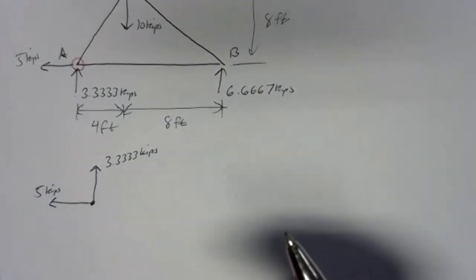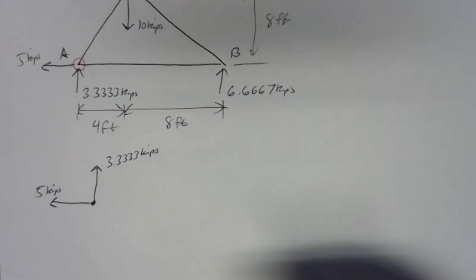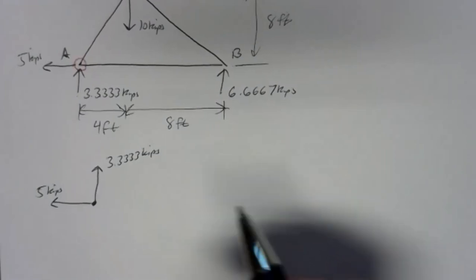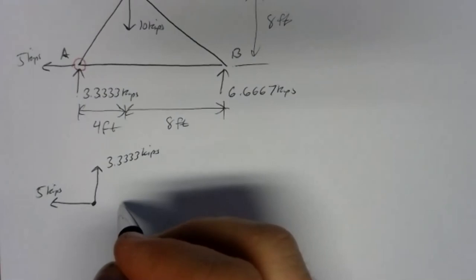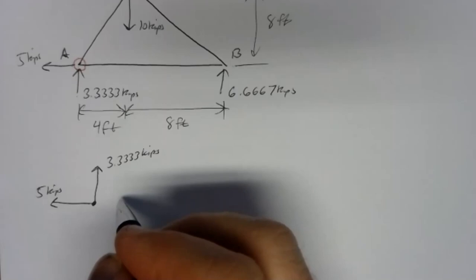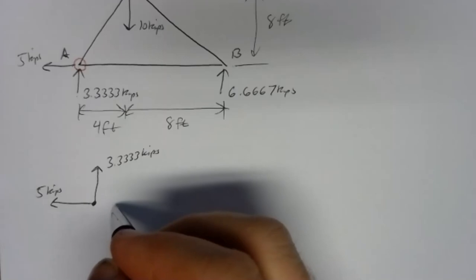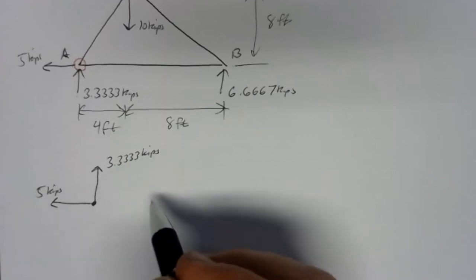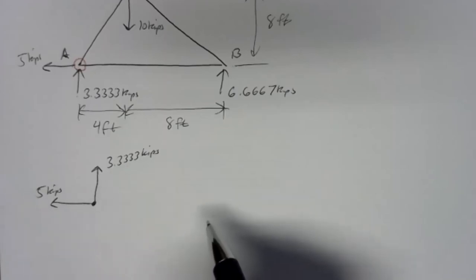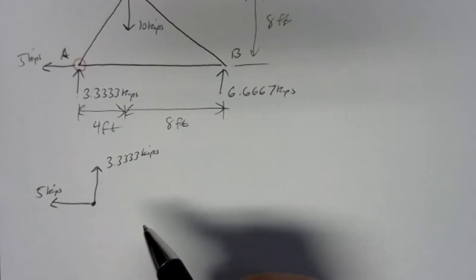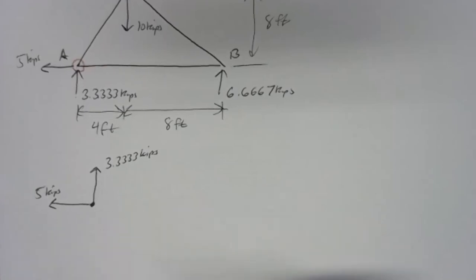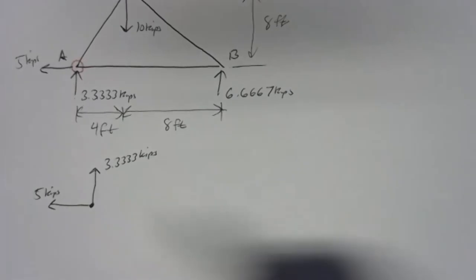And it's not always going to be clear what direction that force is in. Sometimes you just pick which direction based on what's going to be easiest to draw in the free body diagram. So you're going to make guesses here, and hopefully they'll be intelligent, educated guesses, and a lot of times they will be, but sometimes it's complex enough that you really can't make a good guess. So be assured, though, that any guesses you make will be sorted out by your math. Same method that we saw before. If the answer came out negative, then we've got our assumption wrong.